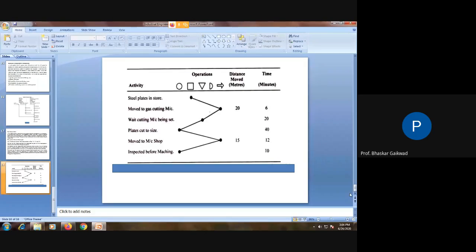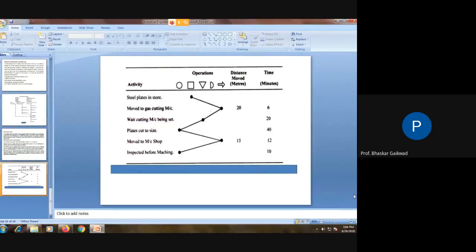So for the operation process chart, what things do we actually require? Operation and inspection. Okay. So once we get the drawing of our washers, then we'll go for the design of the die, maybe a blanking die or piercing die. The design process will be there. After that, we have the machines. Initially, we require the press machines, and once the die gets fit on the press machine, we will have to bring the raw material from the stores.